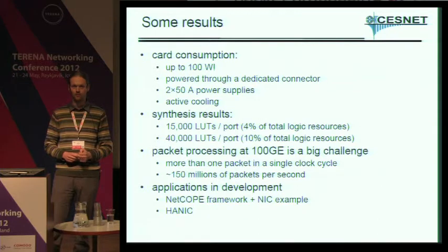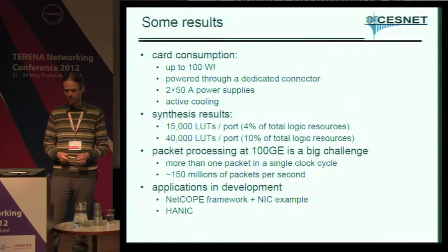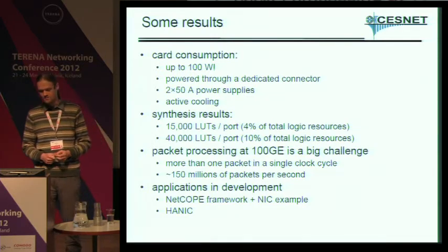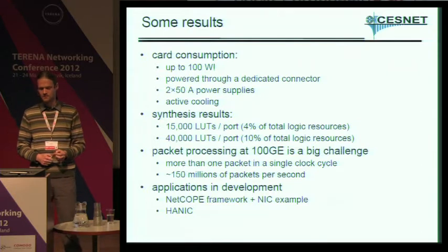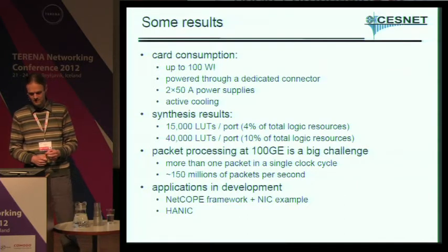Synthesis of the Ethernet IPs, of the Ethernet blocks. For 40G, we get somewhere around 15,000 LUTs per port, of course, which means about 4% of the total resources in the FPGA. And 100G is, of course, much bigger.